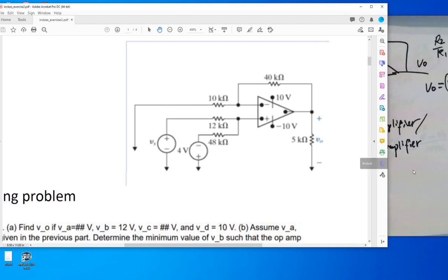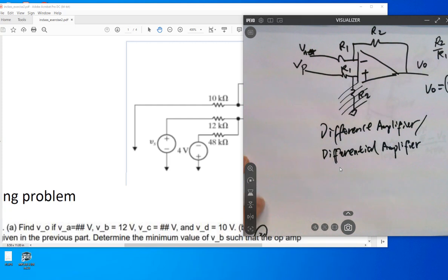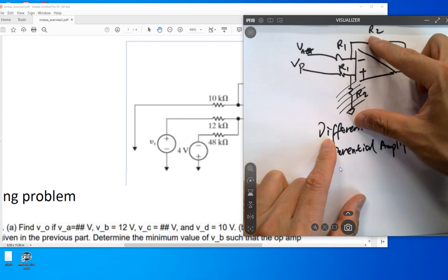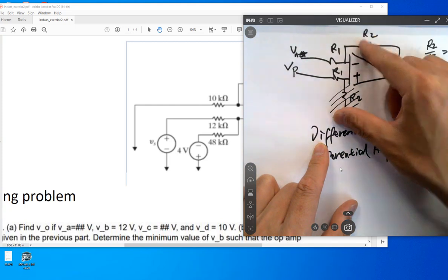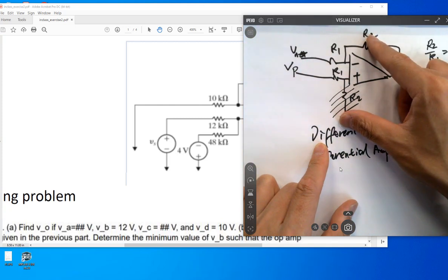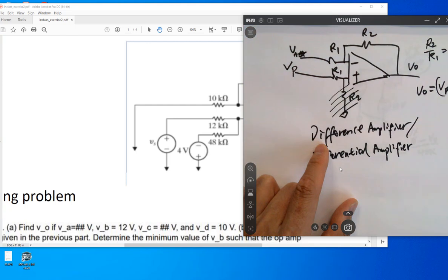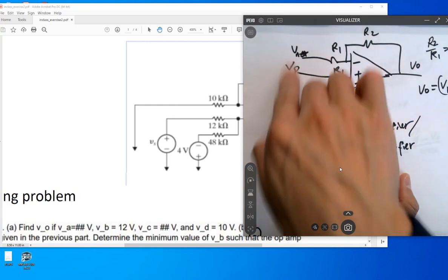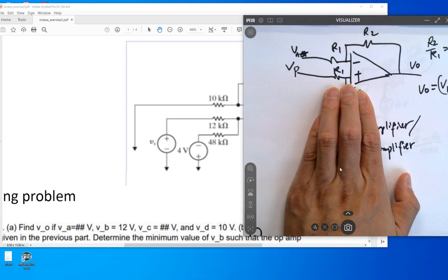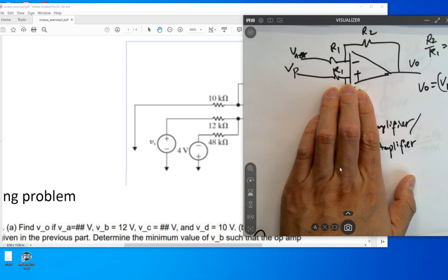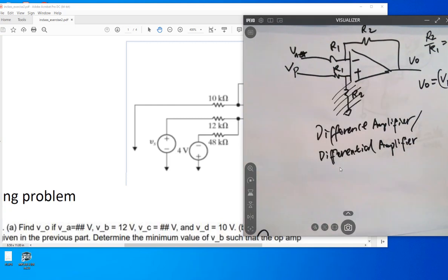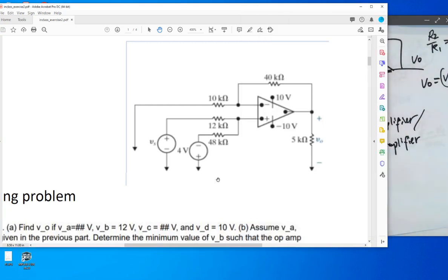If you care about the quality of the signals and low noise, you just use a differential amplifier. But you have to keep this one over here to make it reject noises. It's only 2 choices. You don't have other choices, actually. But sometimes in the textbook, in the exam, somewhere else, you'll see this is gone, but you still have 2 signals. So they expect you to identify this is still a differential amplifier. Just let you guys know, okay?